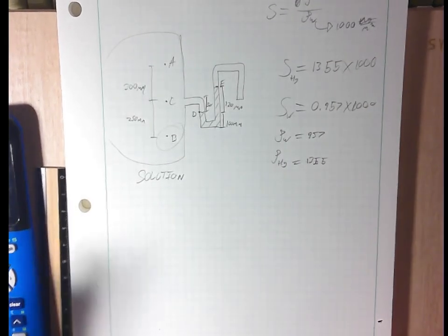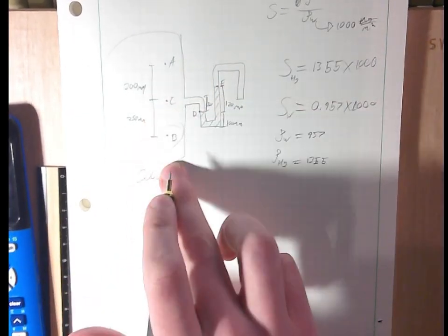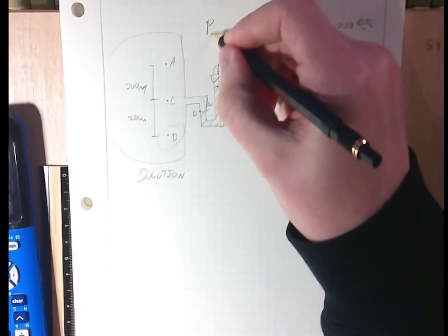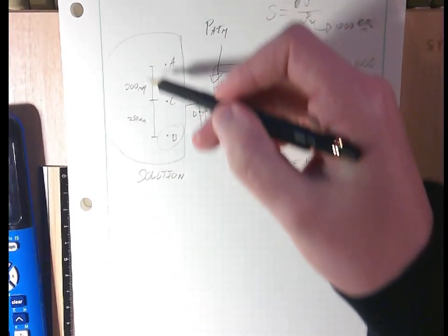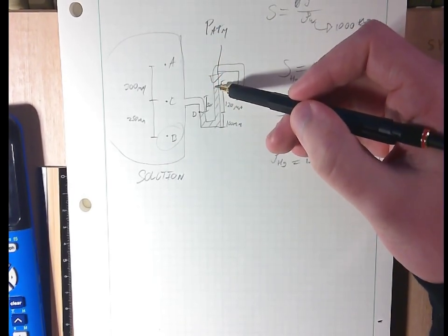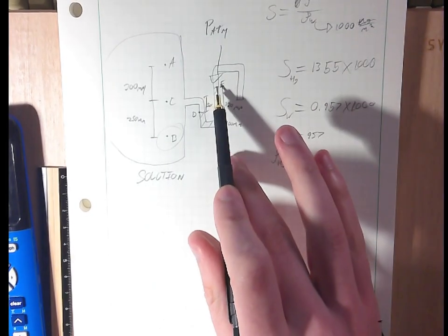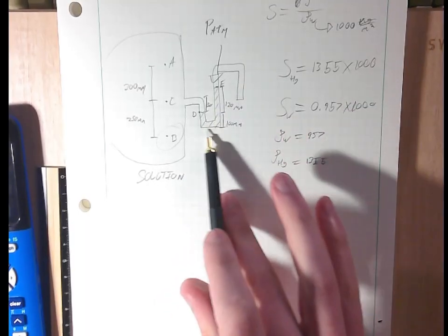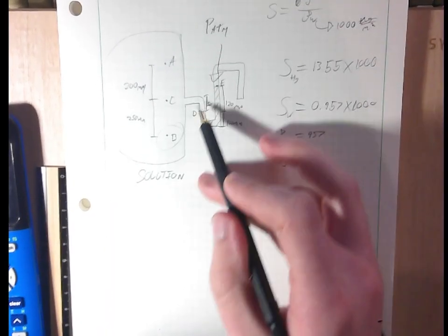So this one's really neat, and I'll show you why this one's so good, because we're basically going to chase the flow of the fluid down from, you always want to do this, from PATM, okay? We don't do it from the top of the liquid here, because we actually don't know where the top is. It doesn't tell us where, okay? But we do see that this right here is an opening. Okay, this is out towards the atmosphere. So we're going to start here. We're going to work our way down over to here in the straightest line possible from point to point. So that means we're going to have to go from point E to point D.